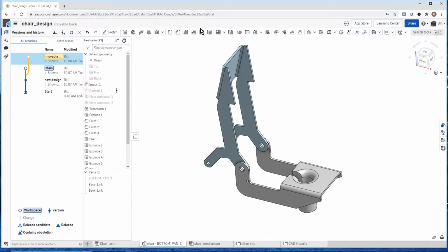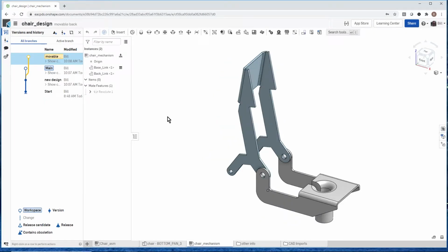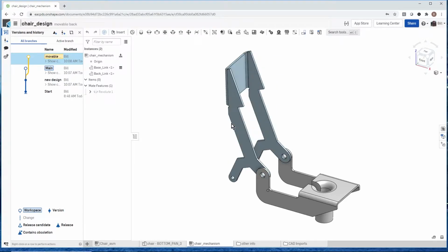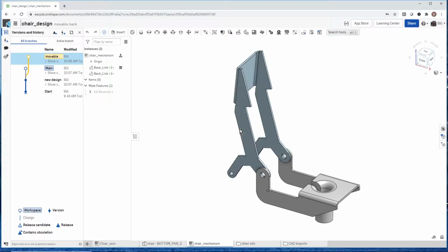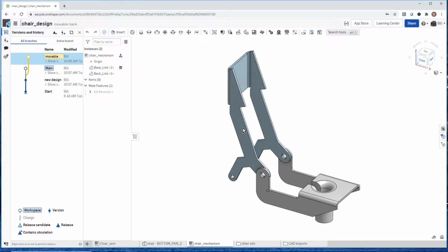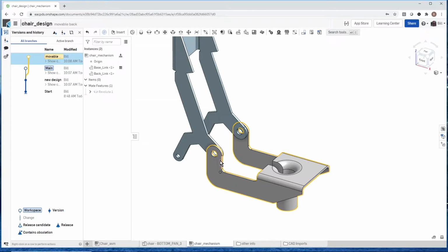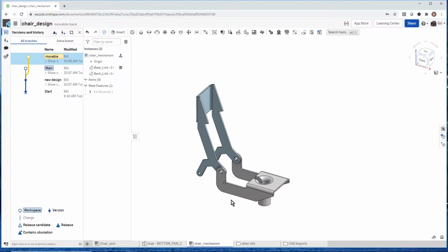You can tell that from the menus across the top. We can do extrudes and lofts and chamfers and rounds and all that type of stuff. Then when I really want to place these two together, because these are kind of fixed at this point, I'm going to put this into an assembly, and now I can add different joints between them. So I have a pin joint on here, so I can take this and articulate it, right? Really, all I did is take those two parts and, instead of having them rigidly put together, put a pin joint or a revolute joint between them.